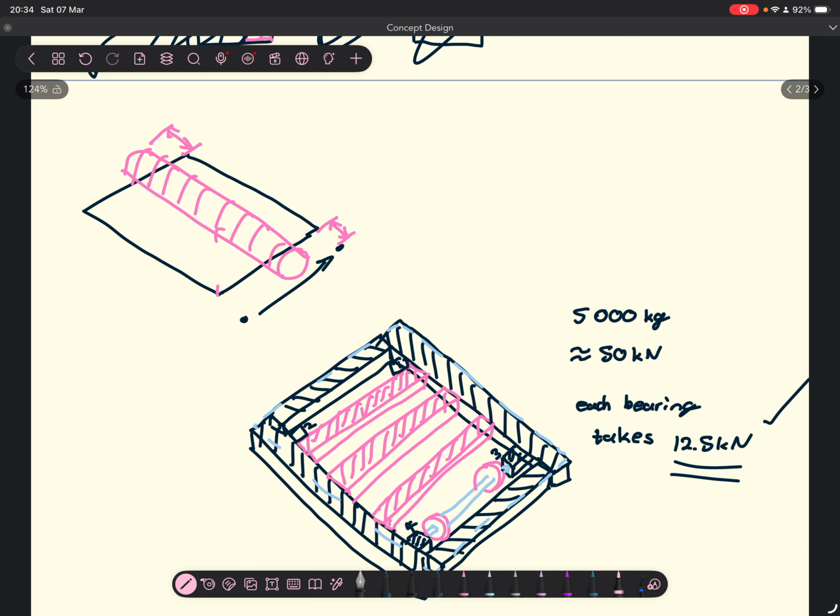And then from there we discussed making a frame. So we just drew the simple shape of how the pipe would be supported. So have a flat platform, and then from there the pipe sits on top. And from there you need to identify which members will carry the most load or will be more susceptible to fail, and then you strengthen in that direction. So from here to here, right?